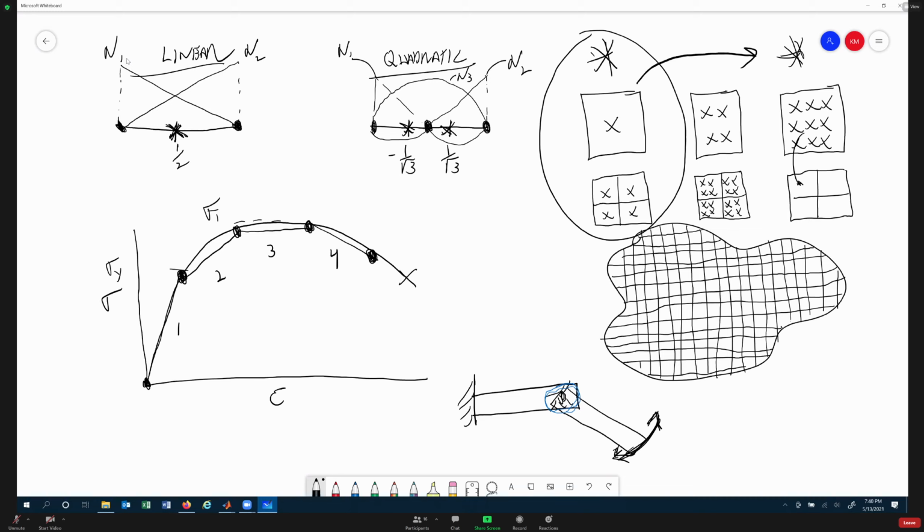And they actually create a loop because they're doing crack propagation work. So they get a stress result as an output, and then they evaluate it and run that through J2 flow theory to see, is it plastically deformed enough at the crack tip to where it actually unzipped and opened up a little bit? They modify their boundary conditions, feed it back into the solver, and do it again. It's kind of an iterative solution that way. So it really just depends on how theoretical the work is that you're doing.